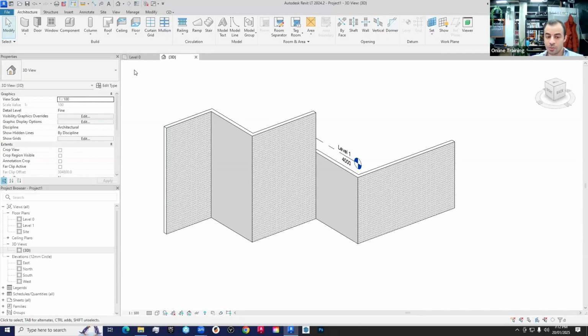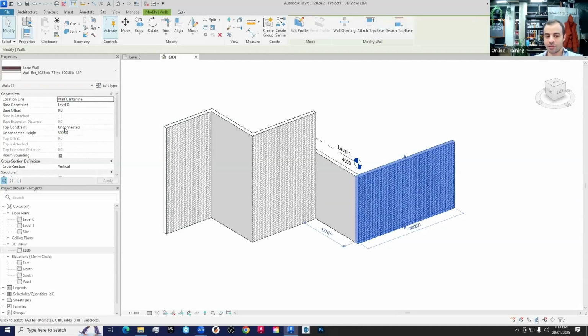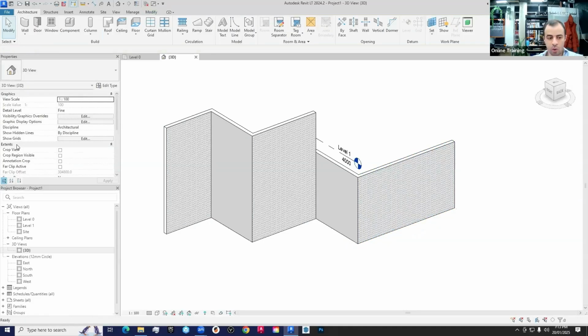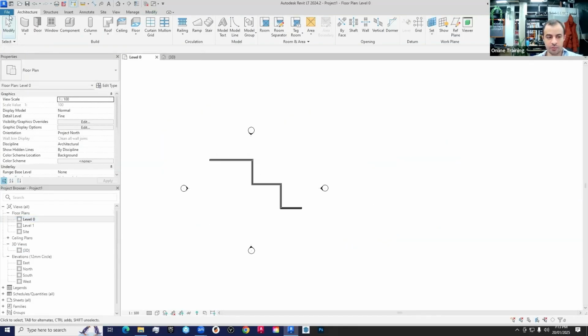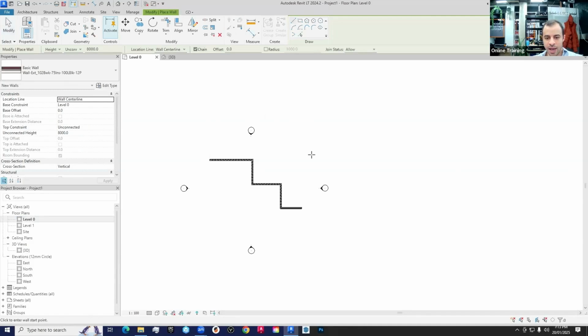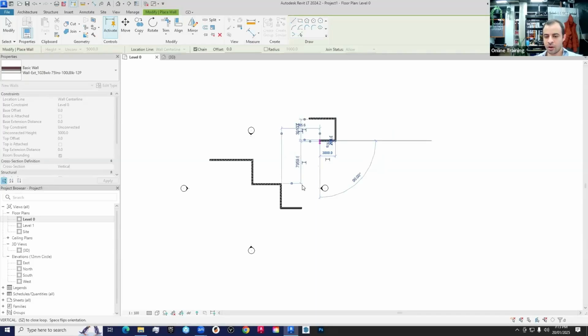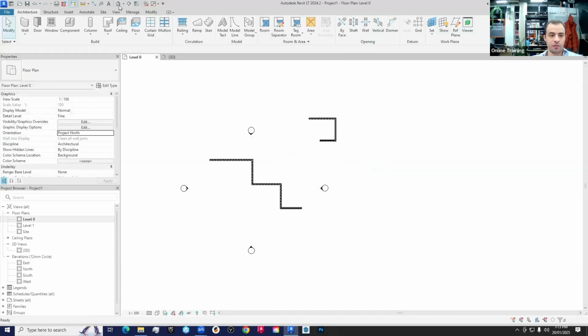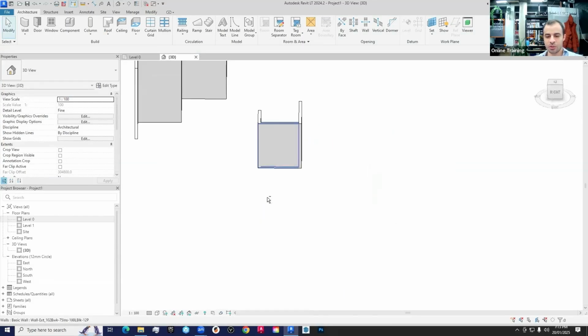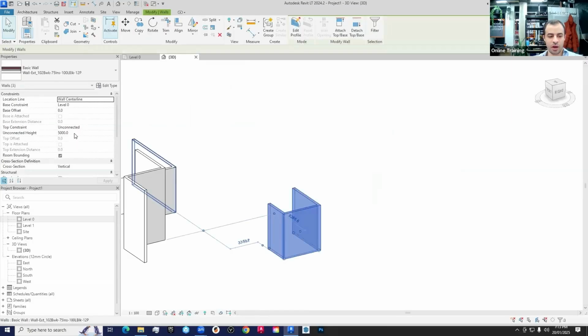Okay, so you can change the properties before drawing the element, during the modeling process, or after finishing things. You can place things and then select them and change the properties later. Or you can model a wall, and as you model it, you can change the height, for example, and I'll add a couple of walls here. Okay, so now if I go to the 3D view, I can see these walls. They come already with the height that I input in the properties right away.